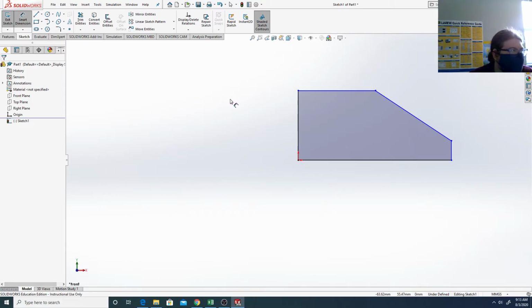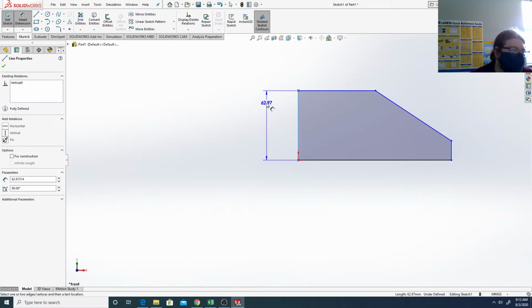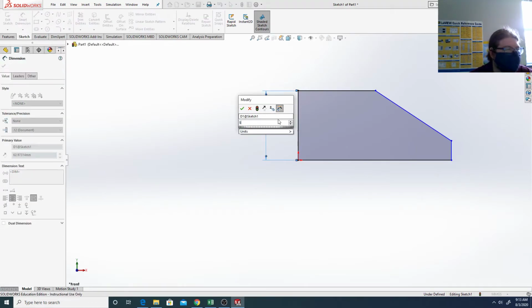And next to my icon, I have that little Smart Dimension symbol floating to the lower right corner of it. To dimension lines, I just need to click on the line. So if I want to dimension this up-down line, make sure you click on the line and not this little point that pops up. So we click on this, scoot over, left click again, type in 50 for the 50 millimeters tall it was